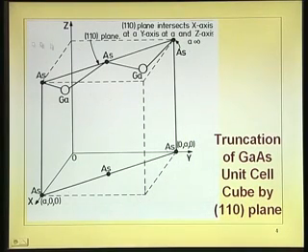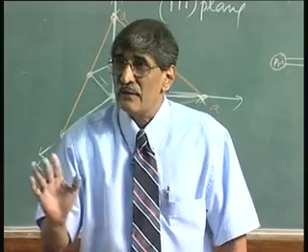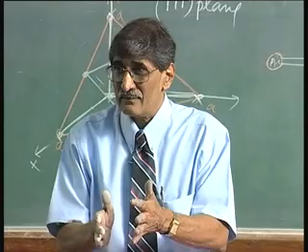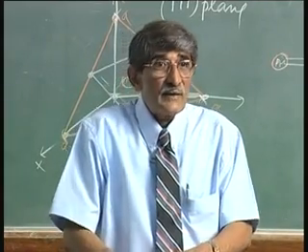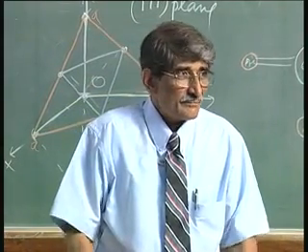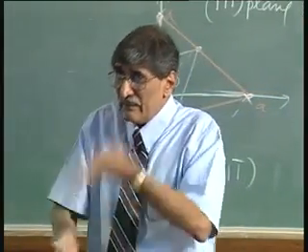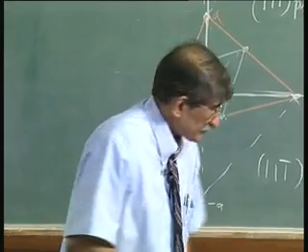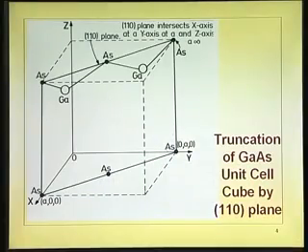this plane. You saw that the number of atoms counted together is 6 here, but the contribution is only 2, and gallium atoms 2. So if you take the entire plane, the number of gallium atoms equals the number of arsenic atoms: charge neutrality. Between the planes there is no electrostatic force of attraction, it is only the covalent bond. So it becomes easy to cleave in that plane. Between the planes binding is not so hard, so we are able to cleave it. So, the cleavage plane,